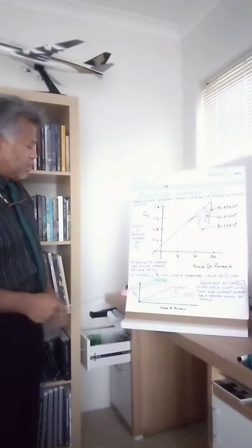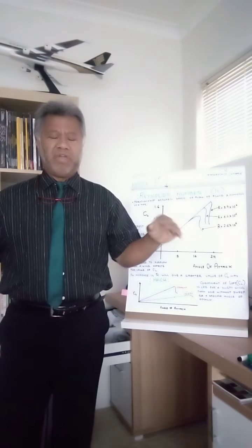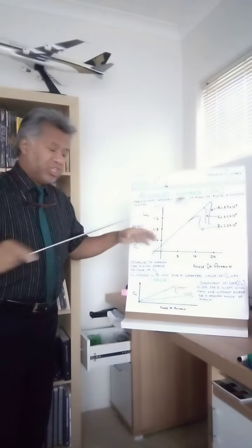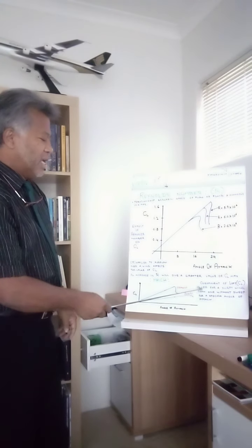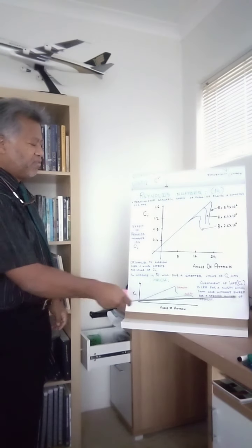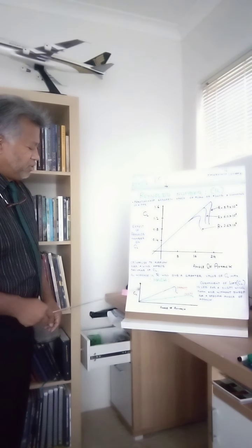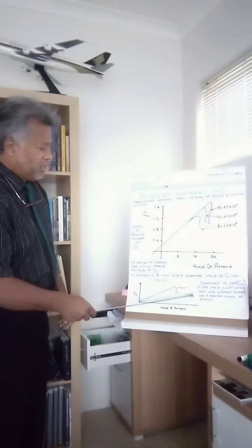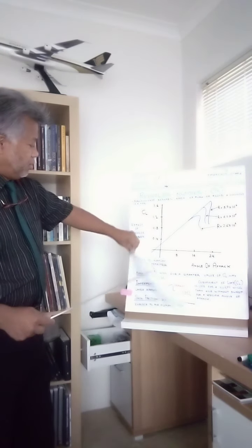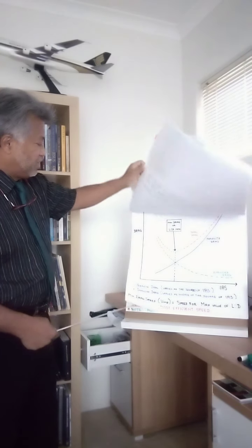The other one we talk about, not in much detail, is the Mach number. Obviously, high-speed performance aircraft have a thinner camber wing aerofoil, and it's usually swept back. So the coefficient of lift is less for a swept wing than one without sweep for a specific angle of attack. As you see, as the angle of attack increases, the coefficient of lift increases at a lesser rate than it would for a straight wing. Okay, so that's the explanation of the factors that affect the coefficient of lift.